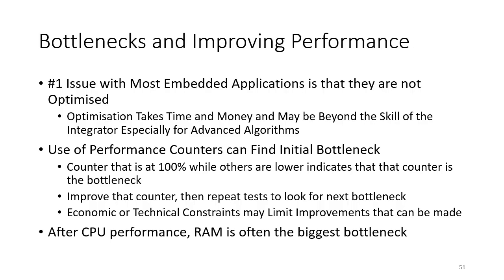If your industrial PC is already 5 years old, you might by now be running an old, outdated operating system, which is insecure. You might be running an old version of the application, if it's say HMI SCADA or whatever. So maybe at 5 years' time, you've got your return on investment. It's now worth looking at that bigger investment in order to do a more comprehensive upgrade of the application to make it faster and more reliable. And often that also comes with additional improvements as well, like cybersecurity improvements.